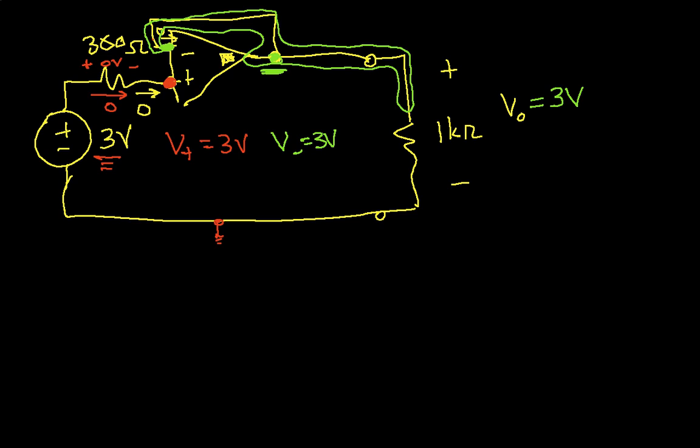So this ends our introduction to the op-amp. Hopefully you've found this useful. The important points to remember are how op-amps work, and that the ideal model, where we assume that V+ is equal to V− and no current flows into the inputs, actually makes our analysis quite a bit easier. You can see that we did this one very easily, where the previous one we had to use nodal analysis and it took a while. So hopefully you found this useful, and we'll quit at that point.